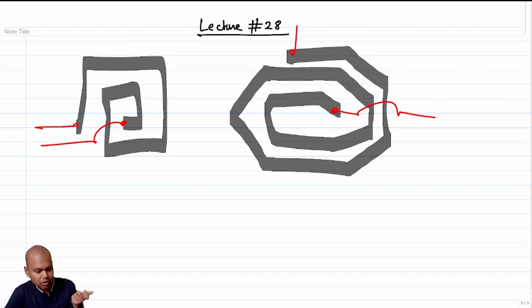Now, as it turns out, in most RF processes, the top metal layer has the maximum thickness, which means it has a minimum resistivity, and the lower metal layers have lower thickness, and they have higher resistivity. So the moment you go to a lower metal layer and you take the signal out, like the way I have shown here, you end up having more losses, correct? So when you have more such resistive losses, you have a problem. So the structure that I have shown here is not a very optimal way of doing an inductor layout.